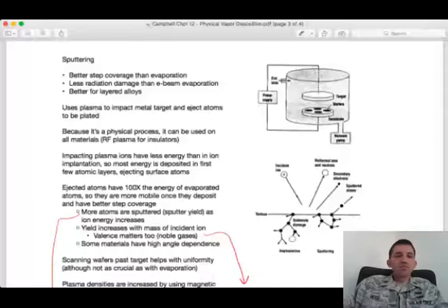If I go back up to talk about this chart with vapor pressure curves, right? You pick a temperature. So let's say I pick, I don't know, 1200, right? Follow that line up. I see that I have titanium at a relatively low vapor pressure. And I go up, okay, there's nickel at, say, 10 times that, go up again. Okay, gold is 10 times that, go up again, right? We have aluminum, silver, maybe another 10 or 100 times. So at one certain temperature, we have much different vapor pressures for different metals, right?